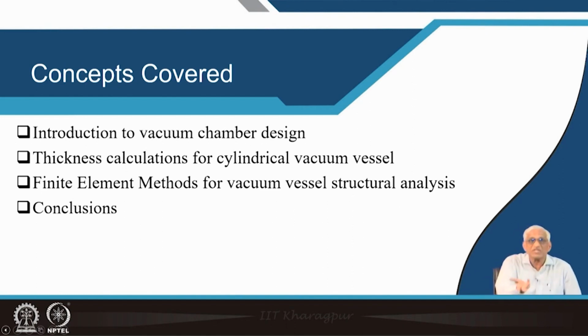Similarly, the surface finish inside is going to be very important. The apparent area that we see with our naked eye on inside surfaces which are actually exposed to vacuum is much less compared to the actual area, because unless you polish it very nicely, just 2 pi r h is not the area of a cylindrical shell. It may be much more because there is some 10 micron bad finish.